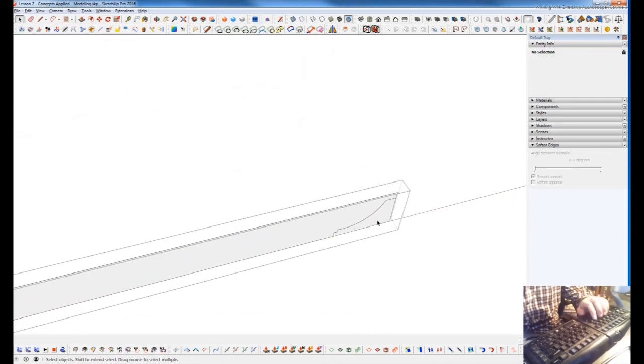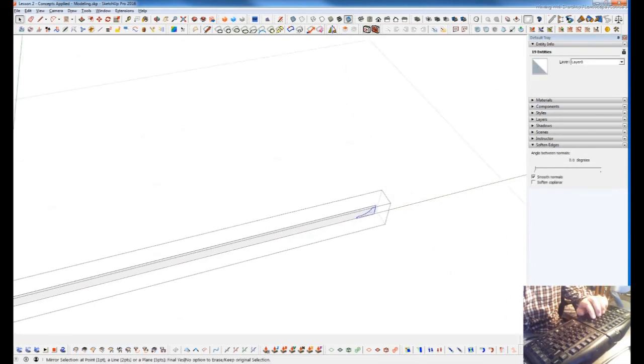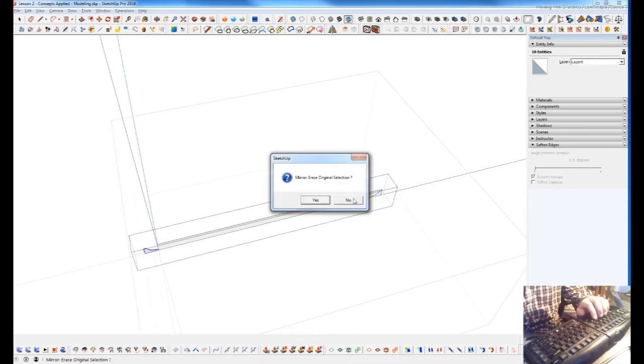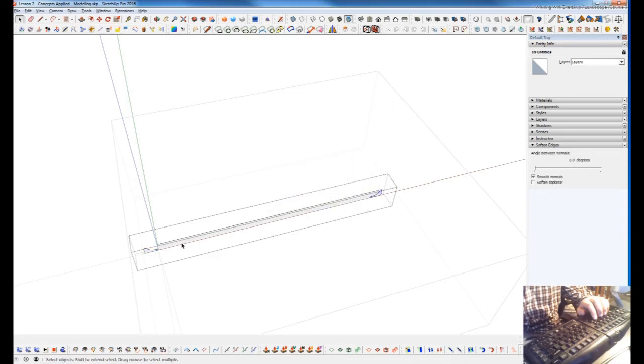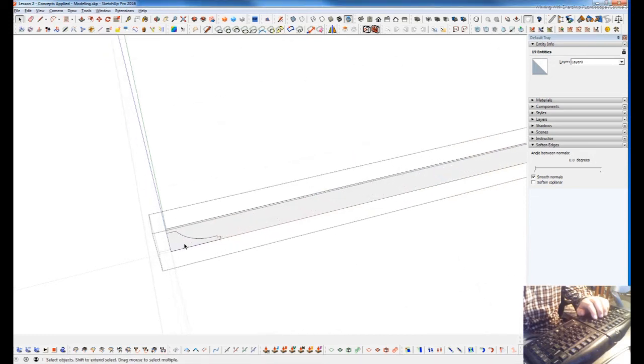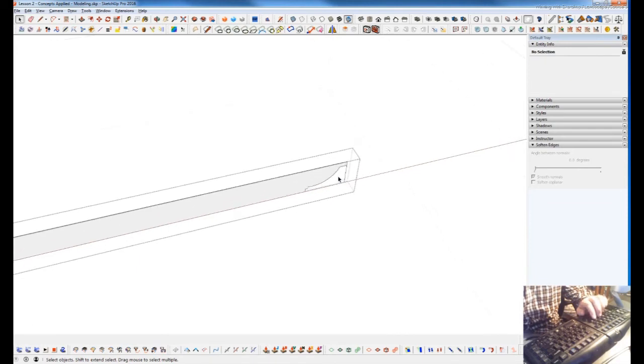Select that, group it, delete it. Or before I do that, I may just grab that set and just mirror that across. Speed this up a little bit, create my little net option here. And that went too far because I mirrored from the bottom, and the bottom has a cut, so this edge isn't as long as the top. So I'm going to undo that, and I'm going to grab this from the top and come up, green and blue, and now that should drop right in there. Select that face, come over, select this face.